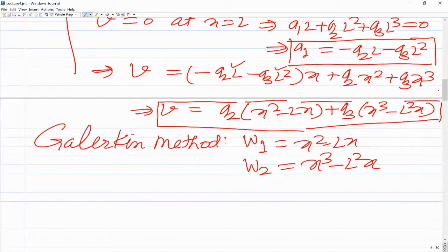Now, one of the most popular and powerful approaches in solid mechanics problems is what we call Rayleigh's method, which is based on the minimum of total potential energy. In all solid mechanics problems, you can always write the total potential energy expression, which consists of strain energy and potential of external forces. So you can write that directly. But if we are given a differential equation and we want to obtain that, that is what I am going to discuss next.